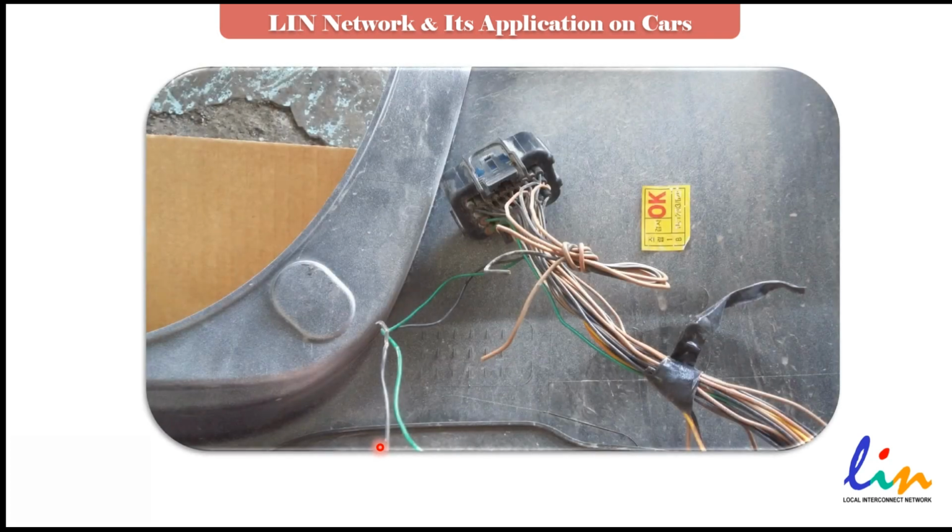And this is what I found. You see these wires? This one and this one. So apparently that guy who was doing the panel beating job, or the one who replaced the rear bumper, didn't know how to fix the problem on a smart parking assistant system. They just cut the connector from one sensor, and this is what you see.